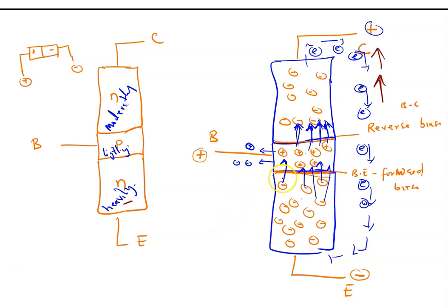So once this is a forward bias region, then as soon as I start operation, the electrons begin to flow towards the base side. Once they flow here, because the P here is attracting the electrons, some of the electrons will be moving to the base side of the terminal, but it's lightly doped. And more electrons are moving there. So because some of the electrons also want to have their way out of the base region of the transistor, they are forced to move to the collector side. Once they get to the collector side, the positive terminal attracts them, and they begin to flow.